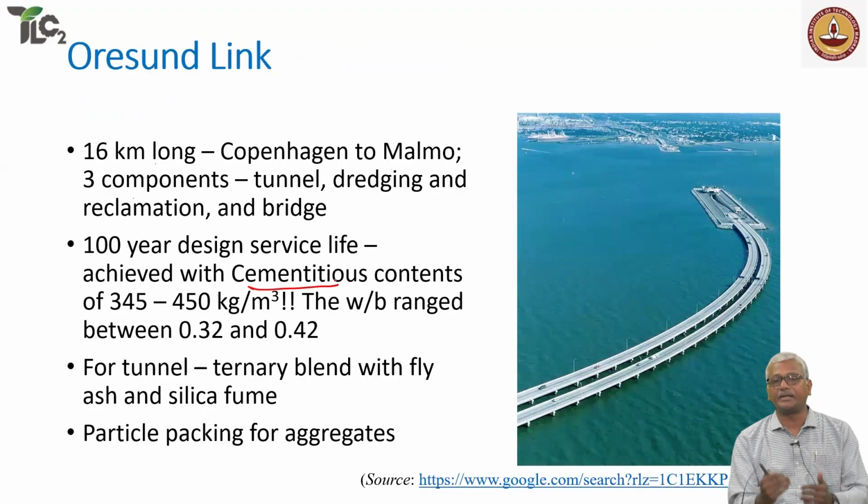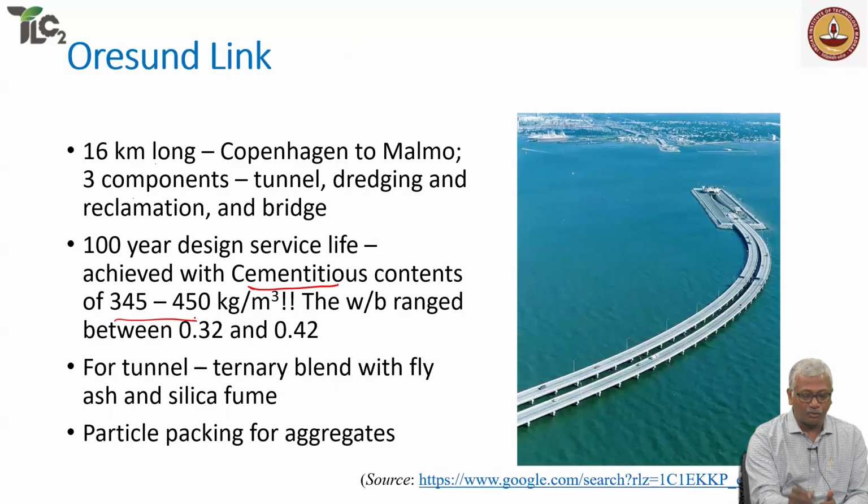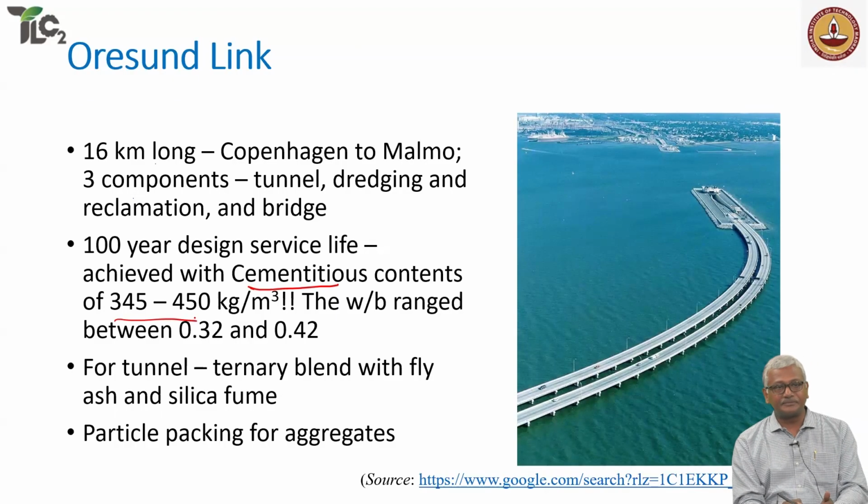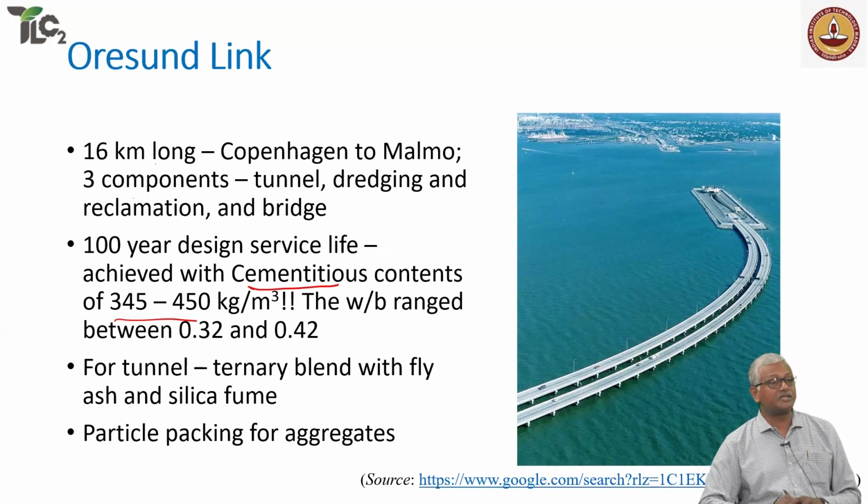That means including all your supplementary materials of 345 to 450 kilogram per cubic meter. Okay, now I'll give you another example later where the cement content minimum prescribed was 450. Okay, now that I'll come back to later, that produced other problems. But here the water binder ratio ranged between 0.32 and 0.42, and they were able to actually control the design life based on that.